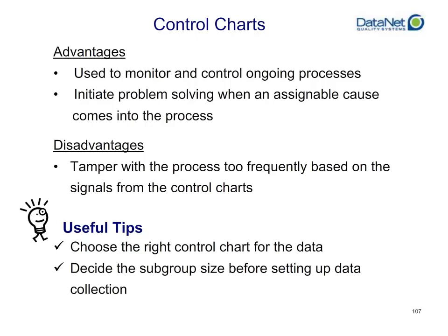You're going to want to make sure that you choose the right control chart for the correct type of data. If you're doing this by hand, this is very important. If you're using software such as WinSPC, this will not be an issue, as WinSPC will not allow you to choose an incorrect chart type that could lead you to incorrect and invalid conclusions.